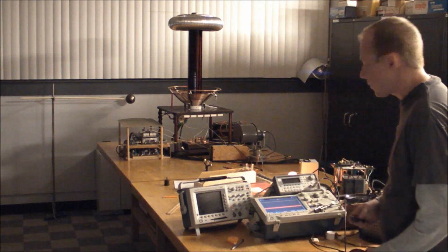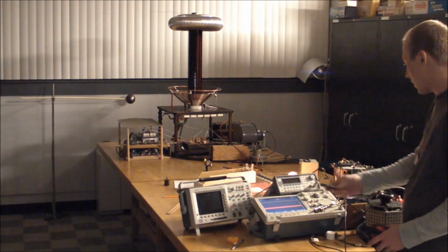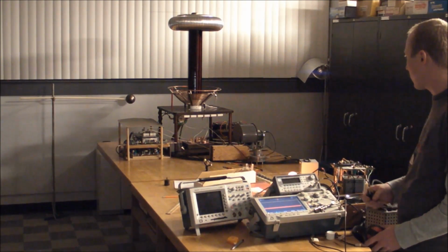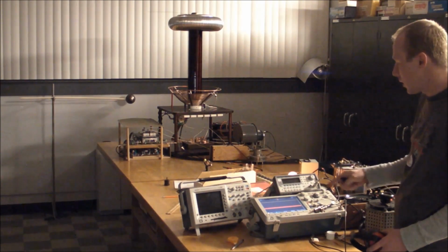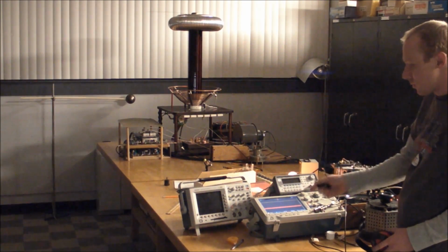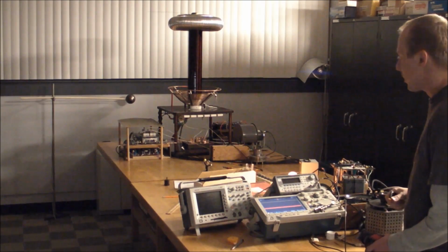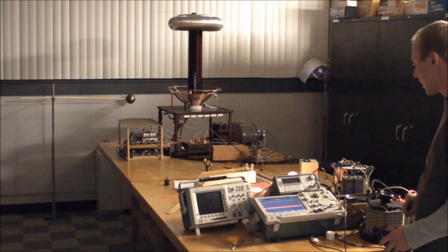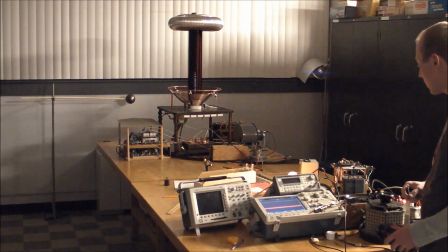And this is what I'll be using to take those measurements. I got my digital scope here all set to go. Each probe is on a different channel, and I'll just use the math function to do channel 1 minus channel 2, or VA minus VB.